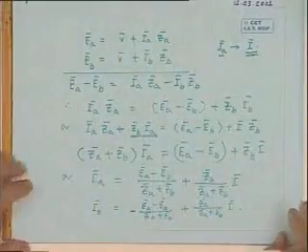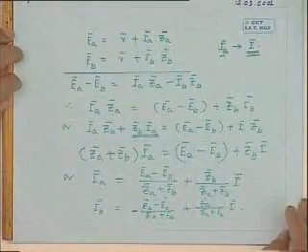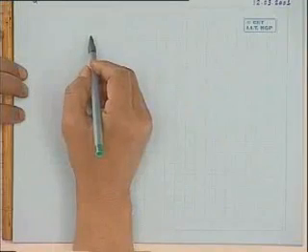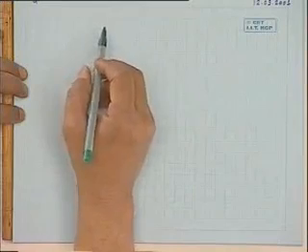Now, it is very unlikely that the two transformers will have the same voltages, even if they are manufactured by the same manufacturer. So the question is, how much should we tolerate this difference of voltages? It is suggested that the difference of voltage should not be so high that the circulating current is greater than about, say, 5 to 10% of the rated current.